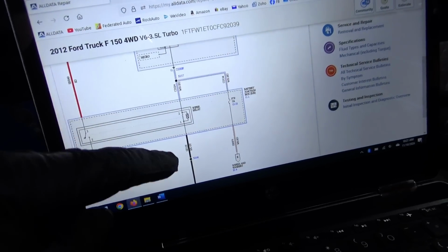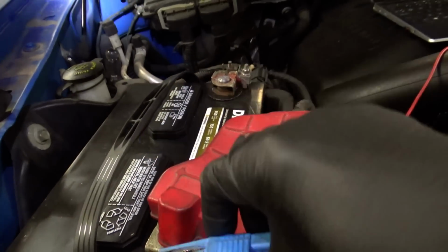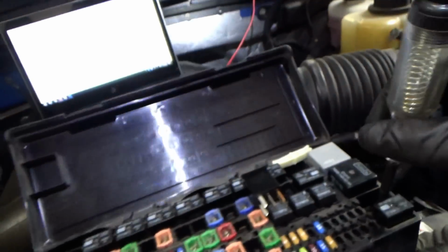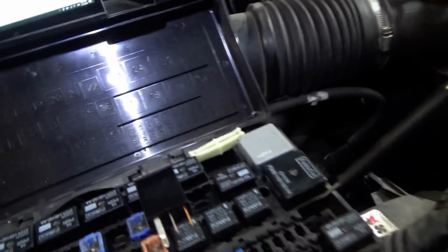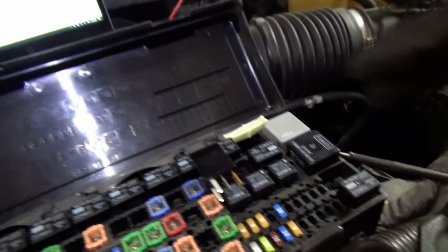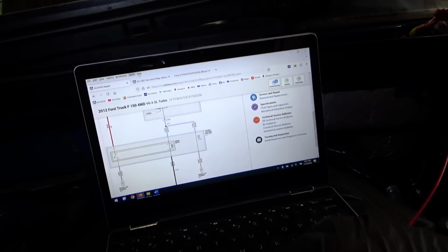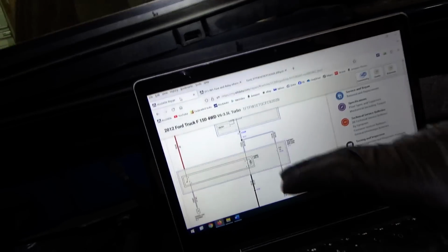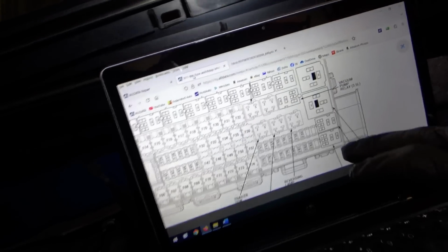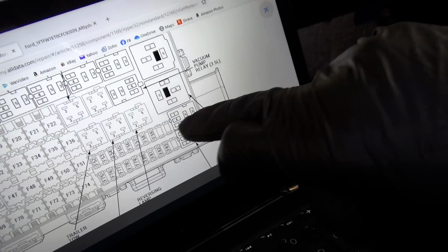So the control wire is this white and blue and then straight to ground. Well, since we're here, let's see if we find the ground, it's going to light up. One of these pins, either pin 1 or pin 2, should be a ground, and well, pin 1 should be the ground, and on this diagram, pin 1 should be in the upper left corner.